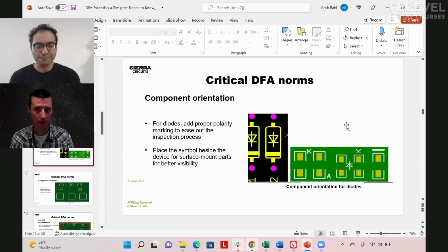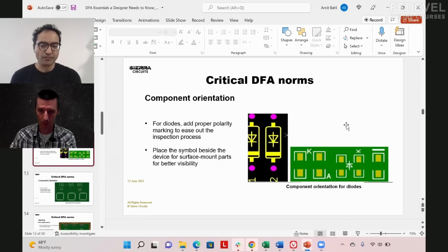Basically, the operator who is setting up the machine always also checks the datasheet of the component, and they have a look where pin 1 is located, and then they look on the PCB or assembly drawing or something, and they place the component correctly into the machine.